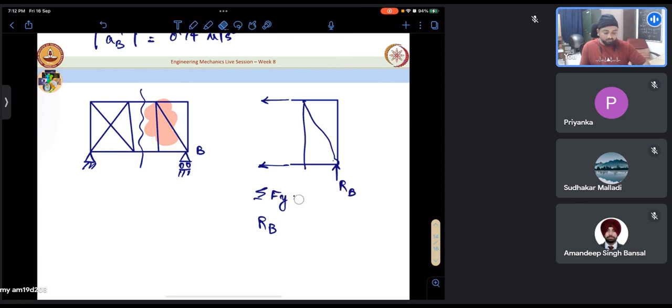So this will not be 0. Some mass times some acceleration will come in here because it is not being balanced. So we cannot blindly say that if m plus r equal to 2j is satisfied, it is holding the stability condition also. It is necessary, but it is not sufficient because we have to look at the arrangements also.